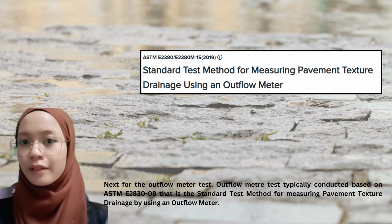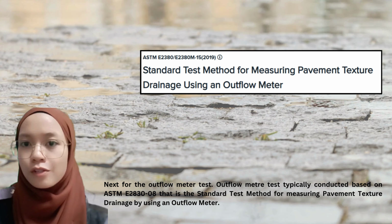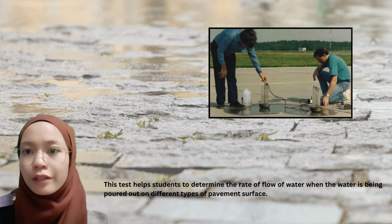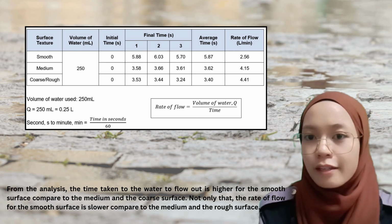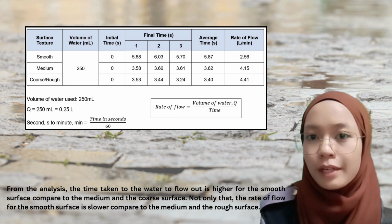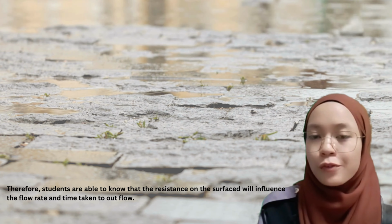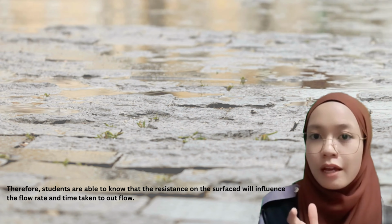As for the outflow meter test, it is typically conducted based on ASTM E2380, the standard test method for measuring pavement texture drainage by using an outflow meter. The test helps students determine the rate of flow when water is poured on different types of pavement surface. From the analysis, the time taken for the water to flow out is higher for the smooth surface compared to the medium and the coarse surface. Not only that, the rate of flow for the smooth surface is lower compared to the medium and the rough surface.